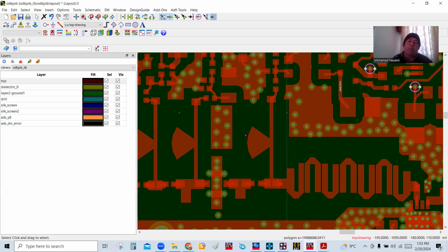So I have two quarter wavelength sections, one loaded with a short, which means its input impedance will be high, open, and the other quarter wave transformer is this radial stub, whose load is open, so therefore its input impedance is short. This is what we want to verify right now by cutting this section and doing analysis on it.